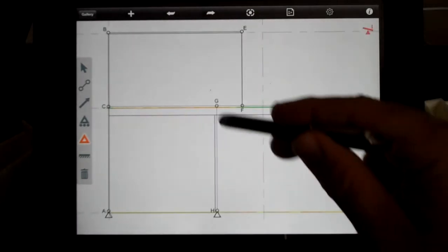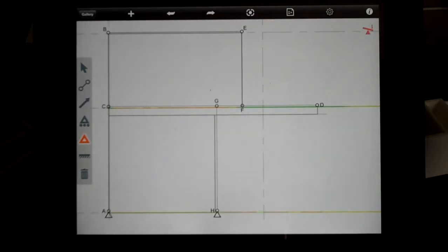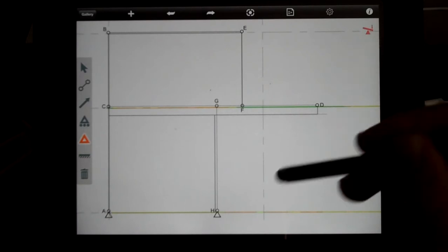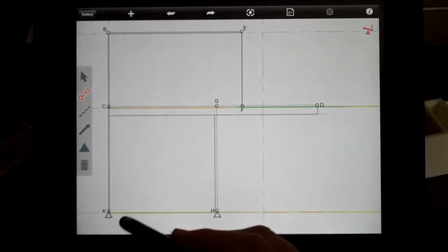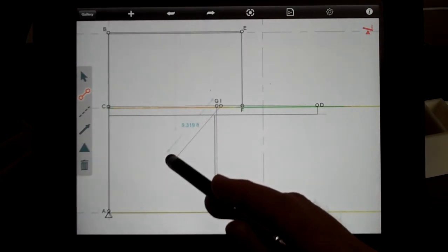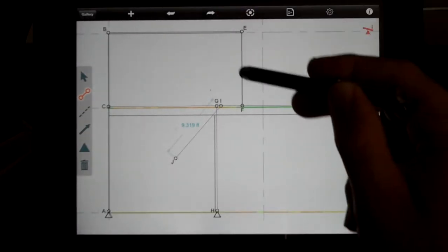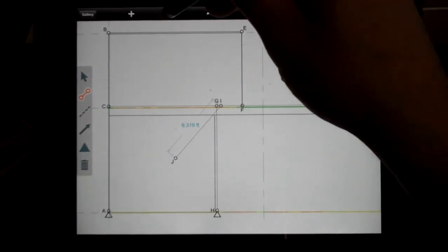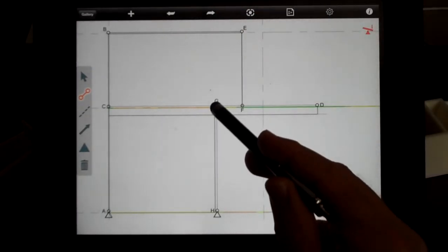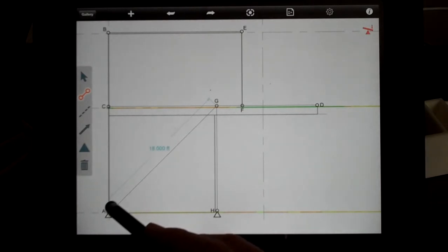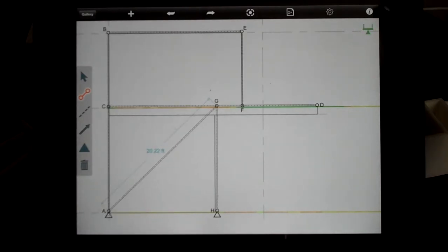And if you notice, even though I have this currently put together, this is still sort of an indeterminate structure. So what I need to do is add in 1 cross brace at a certain location to make everything rigid, and this will allow the software to solve for the overall calculations. And you can see once I have this icon, I know I can start adding in forces and get reactions.